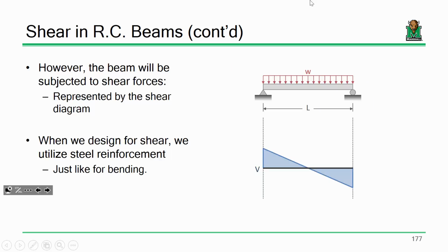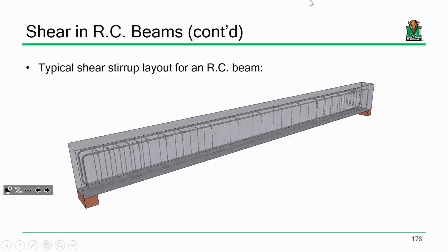If you look at a shear diagram, the shears for a simply supported beam are larger at the supports than they are in the center. So if you look at the stirrups, you've got a really close spacing of stirrups near the support, but out in the middle, they get spaced further apart because you don't need them. At the very least, you're going to need tensile rebar and the stirrups. But to tie everything together in what we call a rebar cage, it's pretty common to put a couple pieces of rebar up top. So more often than not, compression steel is there.